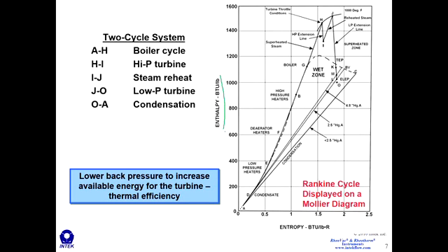or energy per pound in the water throughout the steam cycle, versus the entropy, or the energy that does not contribute to work. It's essential to understand this chart because it's really the basis for developing an understanding and developing algorithms to determine the efficiency of power generation. And it's a great tool to describe why we care about the condenser. So if we walk through this Mollier diagram, we start at point A here, which is down here in the lower left-hand corner.